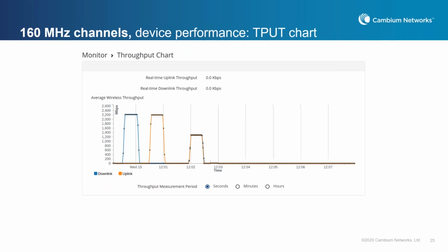Okay, so there are some questions. Well, there's a general question about what kind of range can we expect with this next generation of technology, just in general. Anybody want to jump on that? I think the thing you have to keep in mind, as Dimitri highlighted, is that Link Planner is a great way to look at this, but you do have an EIRP limit with 6 gig. So if you specifically think about 6 gig, that's the best way to calculate that. But as I mentioned, we see a 2-mile link with gig throughput in each direction. We're just getting some more data, and we're going to have some results out of our labs in Cambium as well.